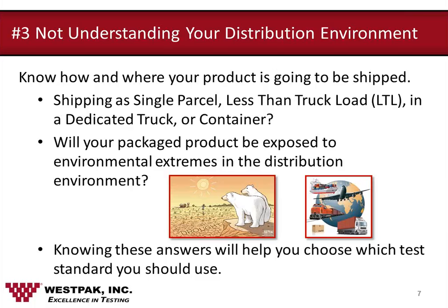Also, will your packaged products be exposed to environmental hazards during distribution? Are you shipping it in a temperature-controlled vehicle, or is it going to be left up to the local environments, or are you going to manufacture it overseas in a hot, humid environment and then ship it to Alaska where it's going to be freezing cold? These are things you need to know prior to testing. And again, knowing these things will help you answer the question and choose what test standard and what packages you need to design.